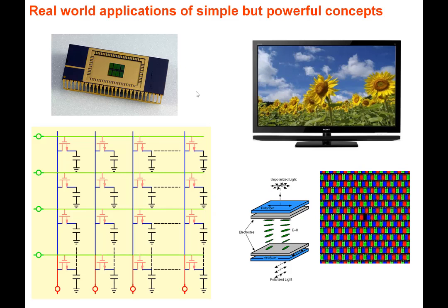For example, when you take a DRAM, a dynamic RAM memory, if you look at it, it is a transistor and a capacitor. Each cell is basically a transistor and a capacitor. So when a student is studying a capacitor, of course we say Q equals CV and all those equations that are there, but a capacitor acts as a memory. It's a basic memory element that is used everywhere. Capacitance is the memory element. And then when you make a DRAM cell, this transistor acts as a resistor here. So it's basically an RC circuit.